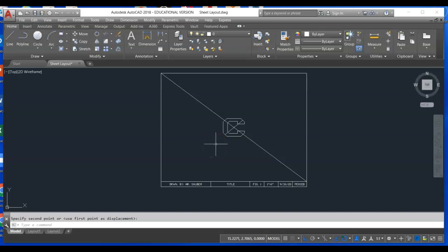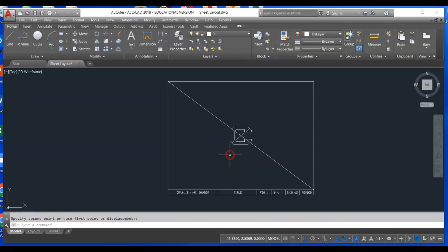So take note that the channel plate is very small. When we start putting dimensions on here, those dimensions are going to be very, very small. So we have an option. We can scale this drawing up. But when we do that, we need to make sure we change our scale factor down here based on what we scaled this object up. So I'm going to do that.